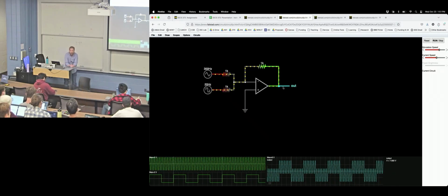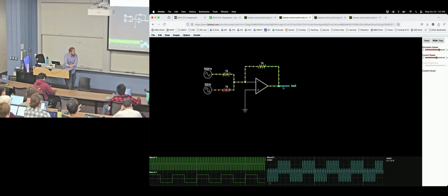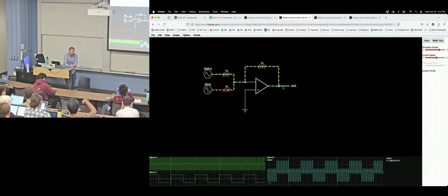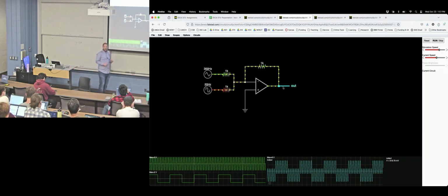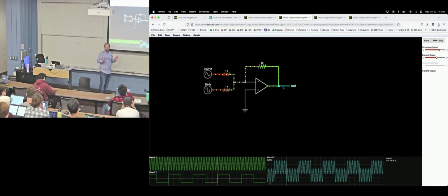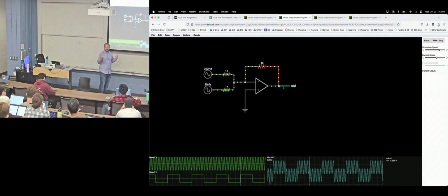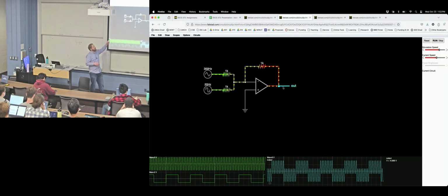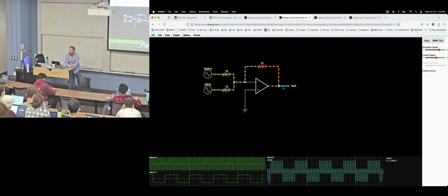Yeah. It's not a direct sum, is it? There's like a coefficient of the output. Yes. But we're going to choose our resistor values nicely, right? Oh, okay. So that happens to all those values are the same, so your amplification factor is 1. However, you're right, if you wanted to, you could change the output resistor there, and then you get a summing amplification. Yeah.